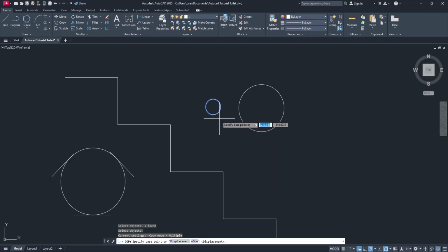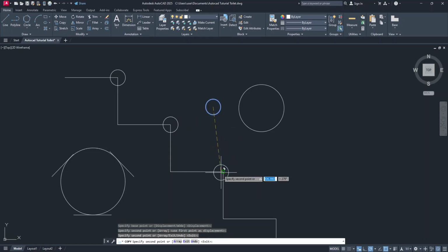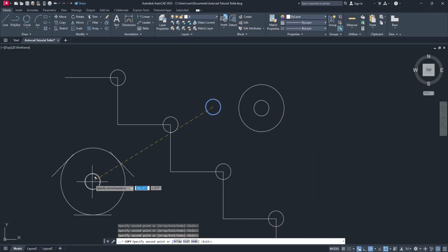You don't click, you just touch it, and then this center mark will appear. Just click it, drop it to an endpoint, something like this. Maybe you want to drop it here, just hover over the circumference, drop one here, maybe one here, just like this. Now I press the escape key.